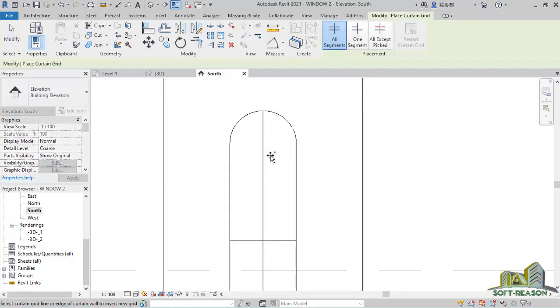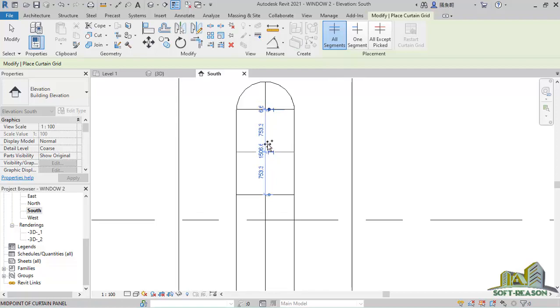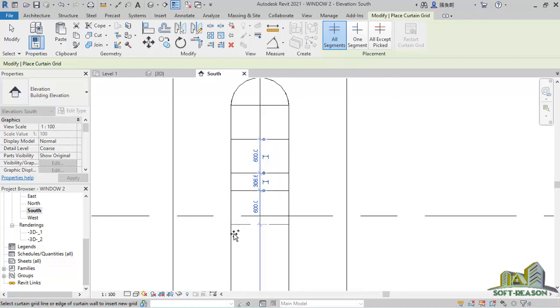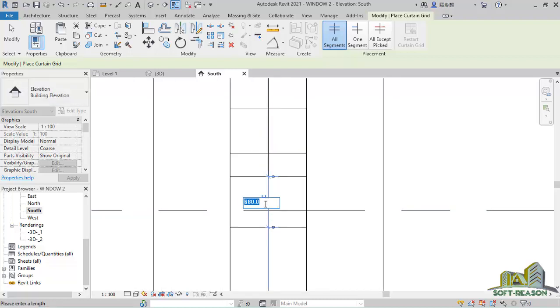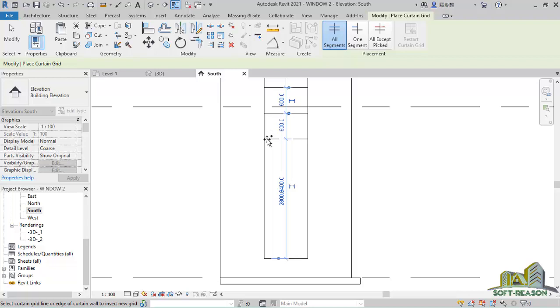go to mullion again, and you can be able to place this one like this, and we'll be placing it at spacing of 600. I want us to place that 600 spaces just like this. You can edit it here, type 600. Edit this point, 600, 600.